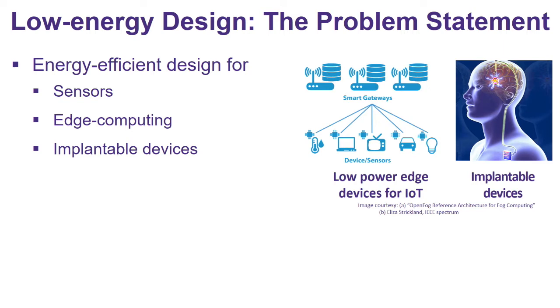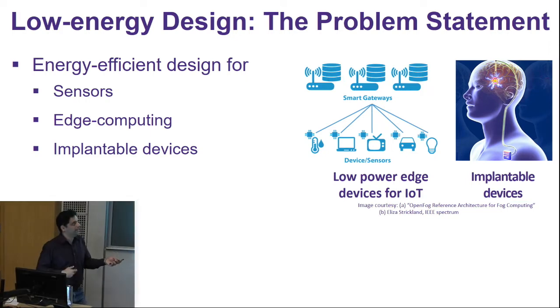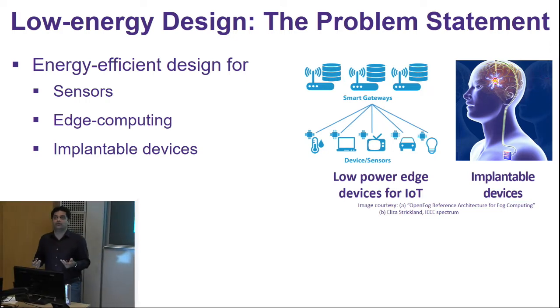It's been around for a while, 2 decades that I'm aware of at the very least. There's been a lot of talk of doing sub-threshold circuits, and a lot of work in that space as well. Very low voltage circuits for very high efficiency. And there are a lot of takers for this. It's valuable in sensors, in edge computing. There's certainly use for it in implantable devices.